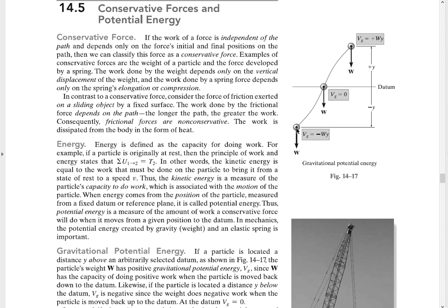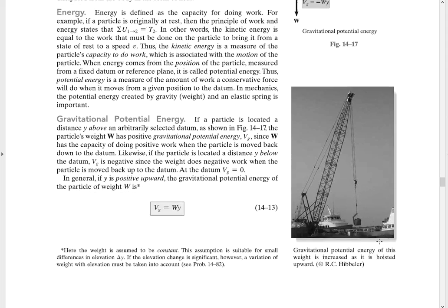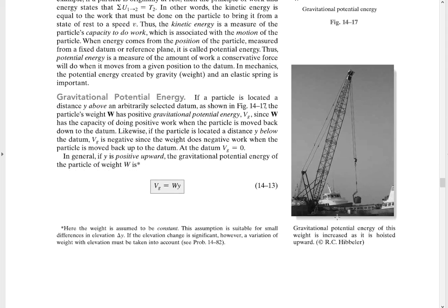So as you reverse motion going with gravity, there is positive work created. As you move up, increase elevation, the work is negative. So the work of gravity ultimately depends only on the initial and final position. But you need to choose a datum and refer to it. You can go below it. Y will become negative. No problem with that. Usually for convenience, we choose the datum like the lowest elevation that the particle could reach. Okay, like yes, of this crane, you choose the ground surface.